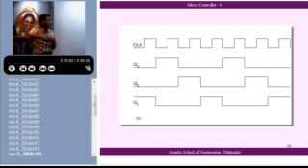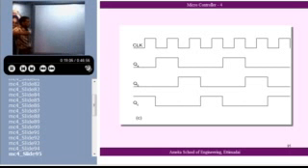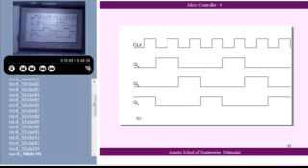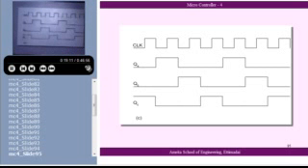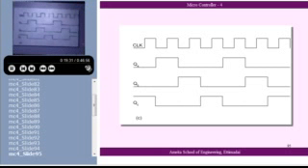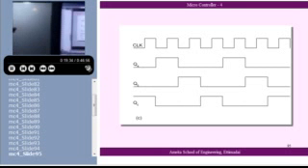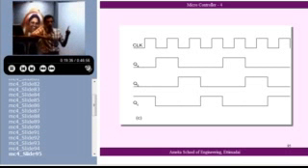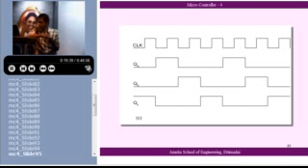Let's see what happens here. I have got a number 0, 0, 1. This number I loaded here. QC is 1, QB is 0, QA is 0. At the clock pulse, this C is getting shifted to A. This A is getting shifted to B, and B is getting shifted to C. This is a shift register. But from the last stage, that output is going as input to the first one. So it will simply go on counting this sequence repeatedly.